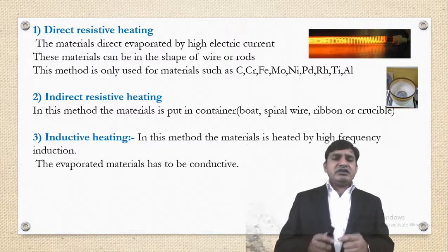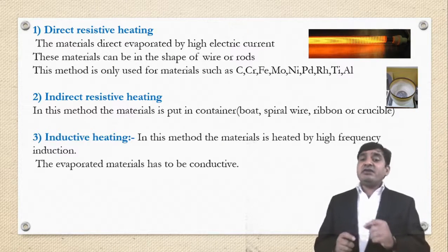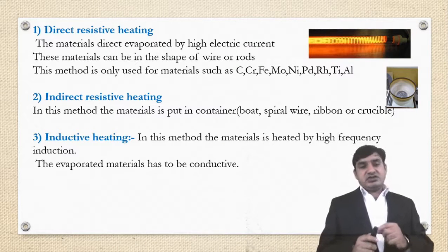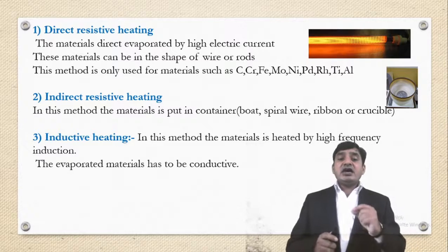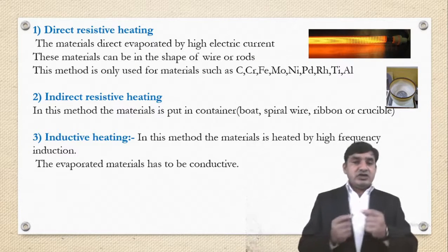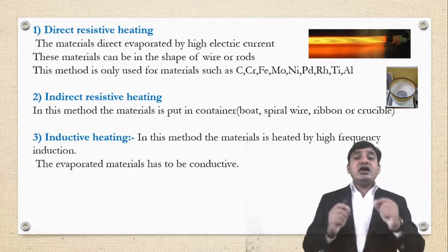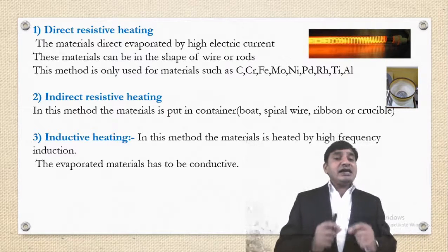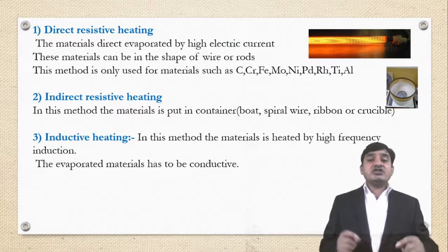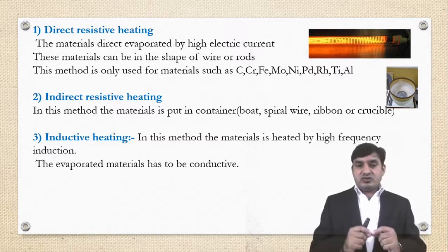Now, inductive heating. In this method, the material is heated by high frequency induction. The evaporated material has to be conductive, and we use the electromagnetic induction phenomenon.